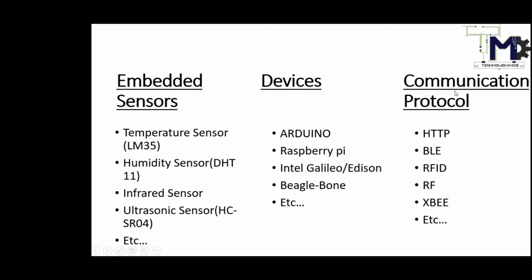The third important part that you must know when you work on an IoT project is the communication protocol. This is really important. Suppose you want to make some home automation for your home, then you cannot go for a very big network communication protocol like 4G or 5G, or something like LoRa. You can do it easily with Bluetooth, right? Because how much area will it cover in your house? Not much. For your home, you can use either Bluetooth or Wi-Fi.